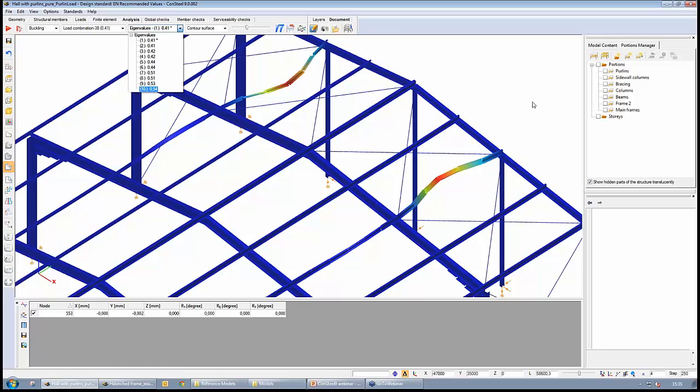It is of course not true, because these purlins are almost completely restrained by the sheeting, at least the upper flange. So this type of buckling mode is not realistic. Then why do we do this? Why do we model this Z purlin? We wanted to model this Z purlin system only because of their stiffness.